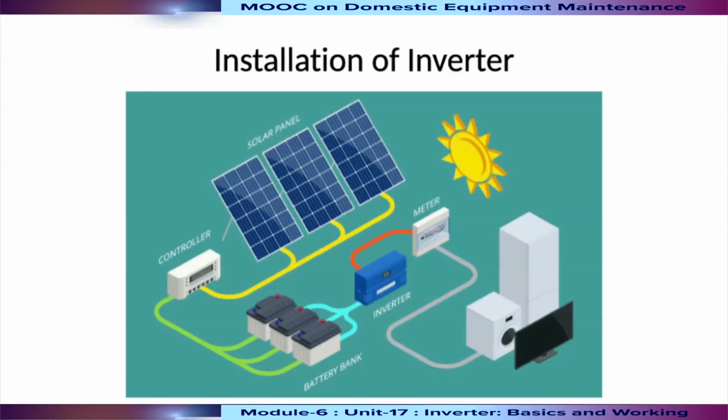These batteries can be recharged by the inverter whenever the battery level goes below a certain threshold. When the inverter is connected to the mains supply, the charger kicks in and starts charging the battery. However, if the mains supply fails, the battery will provide power to the inverter.